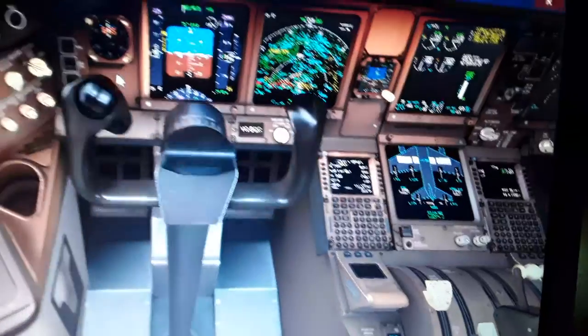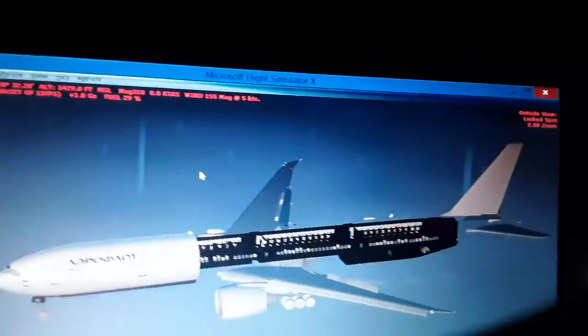So when you pitch up the elevator, you pitch up the nose. When you pitch down the elevator, you pitch down the nose. So you deflect the surface, the flight control surface up and down. That creates an aerodynamic force, a differential pressure in the flight controls that you see here and also outside.